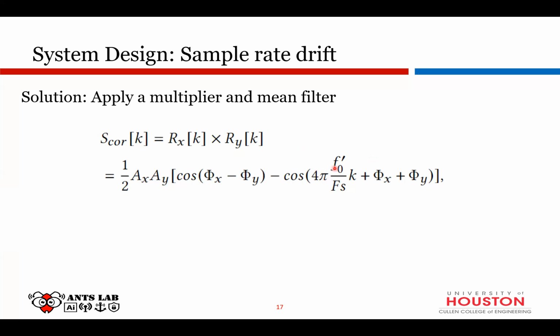Although we do not know the exact frequency of this signal, after low pass filtering this part will be removed, and if it runs perfectly, we'll only have the DC component, suggesting the useful signal we want to transmit. So that is very straightforward.